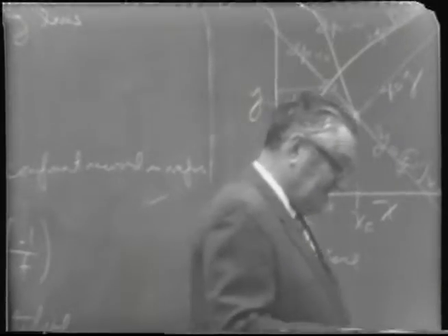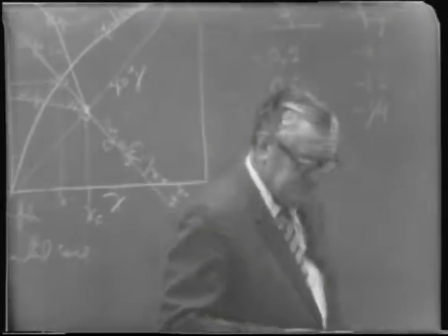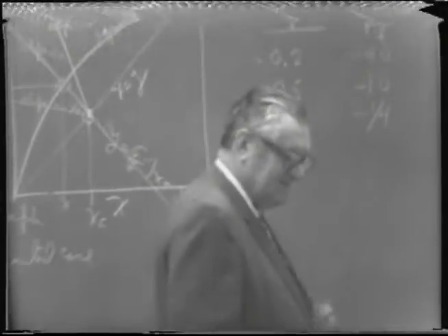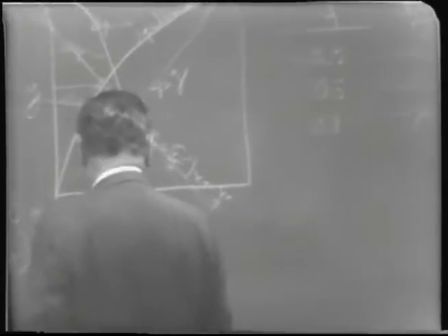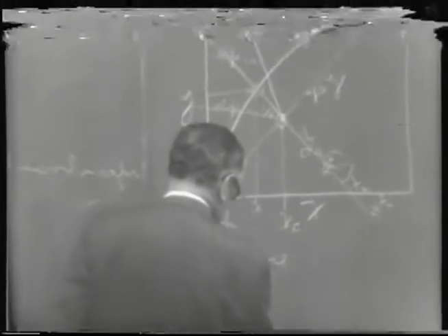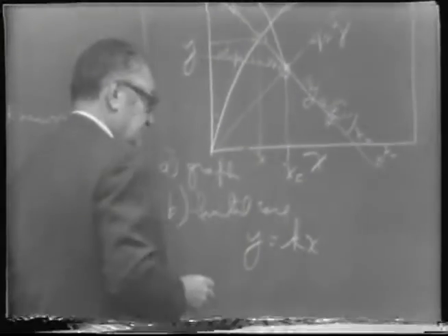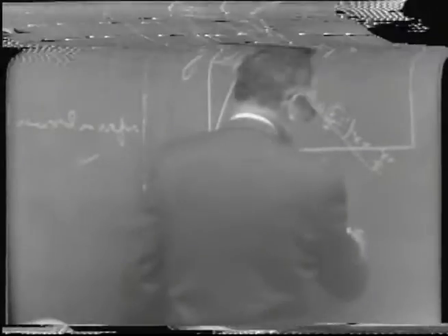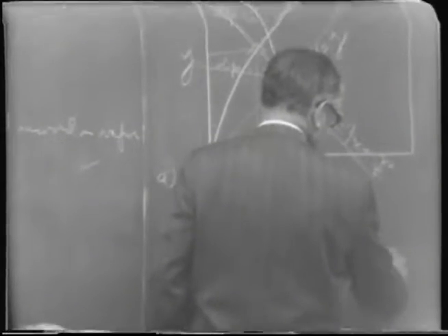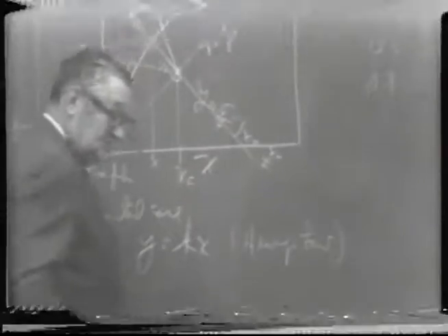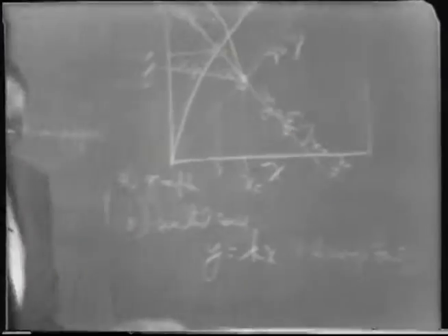Usually the components in that case would be of such dilute concentration that they can frequently be expressed by a limited relationship that Y is equal to some constant times the concentration in the liquid, or in other words, what we call Henry's law, where K would be Henry's constant.